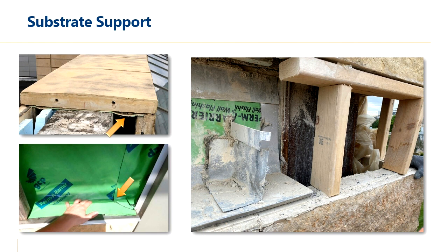On the right, the substrate actually did not continue. Here we have a shelf angle that dives into a vertical column and stops. Instead of continuing the flashing all the way around to the edge of the wall and around the corner, it was discontinuous. They actually stopped the flashing, which meant that any water that was applied or rained on this region and soaked in could run multiple stories down to grade.